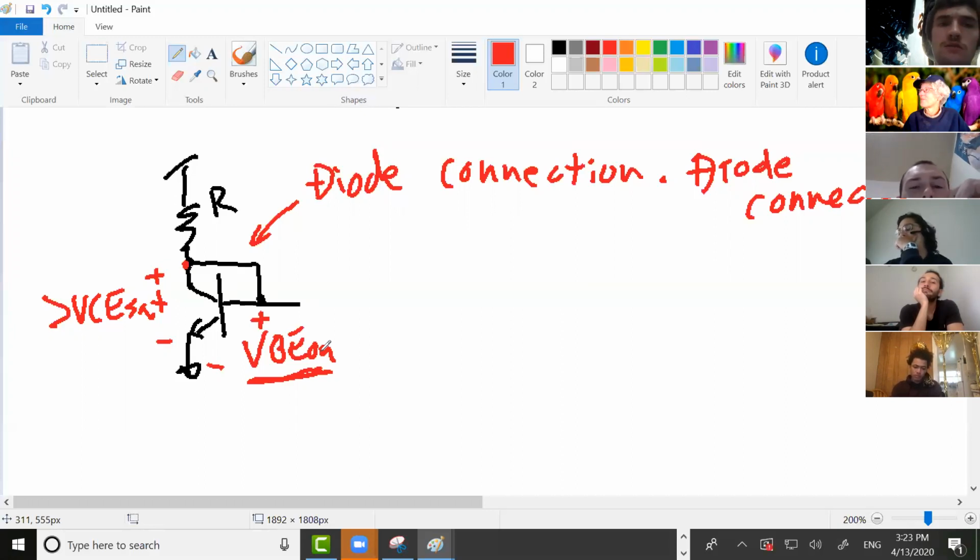Do things just start breaking? Yes, why do they start breaking? Because there's too much current and it gets too hot. So just a small change in VBE changes the current a lot. So this isn't VBE on, but it's going to be pretty darn close.